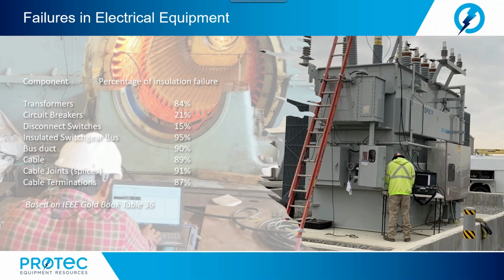Insulation may be deteriorating, however, the equipment may not fail for some time. Although this condition represents a serious hazard, if deteriorated insulation is detected before failure, it can often be reconditioned instead of being replaced. This allows corrective action to be taken during a planned outage before extensive equipment damage results from insulation failure. Power factor testing also makes it possible to detect equipment insulation problems without making an internal visual inspection.